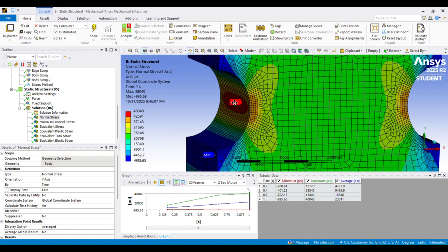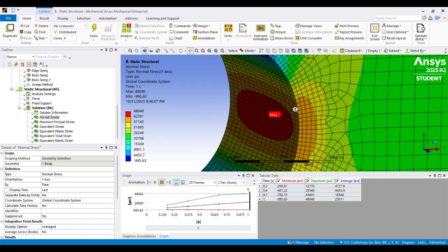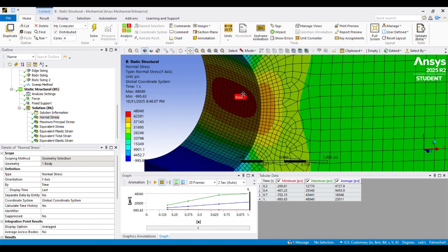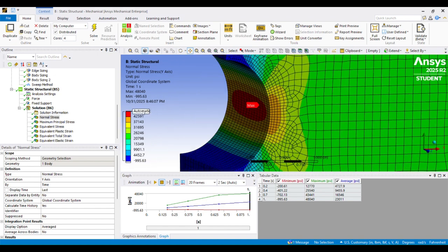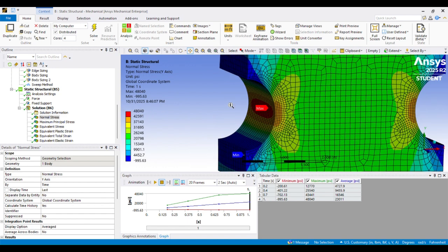we see that it is lower than our elastic stress. Because essentially what's happened is the notch has strain hardened. So it has yielded, so the material has taken up the elastic stress energy, and it's yielded. So the strain has increased, and it has strain hardened.